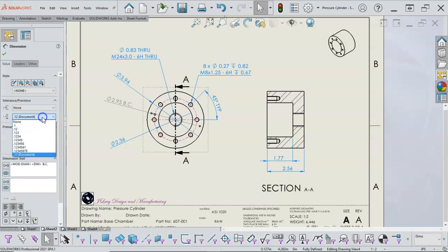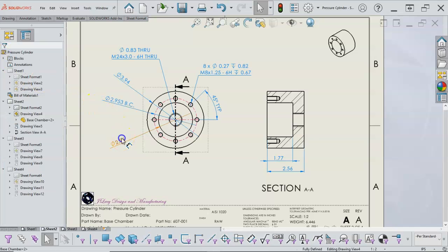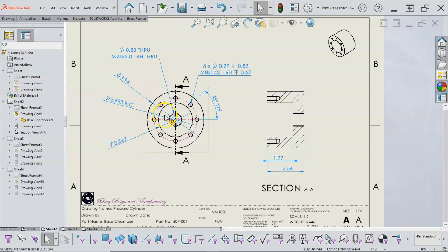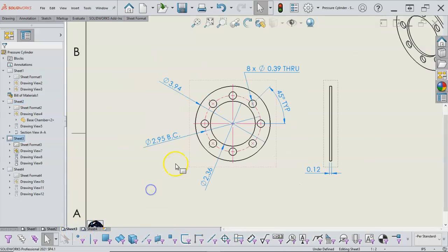But I would think that 3 decimal place for the bolt circle would be helpful. And then the inside diameter would be a critical, just so that we're not having a lot of mismatch in alignment. If the gasket compresses and extrudes into the part a little bit, that should be okay.